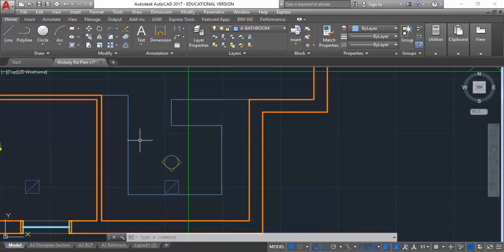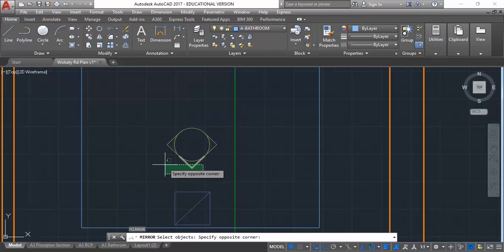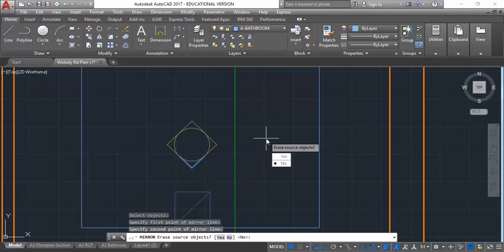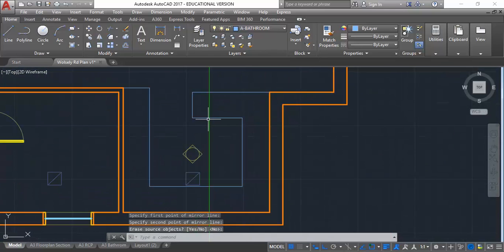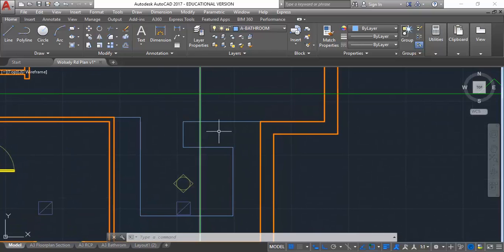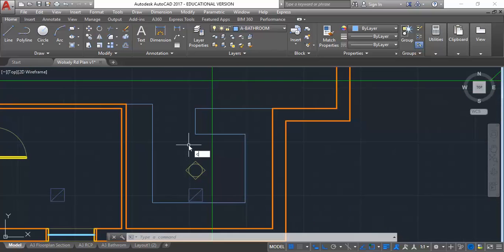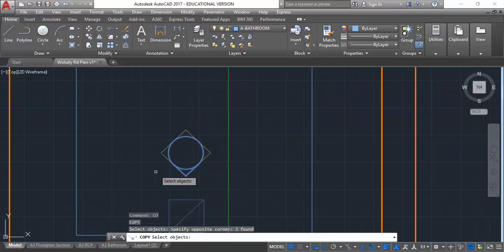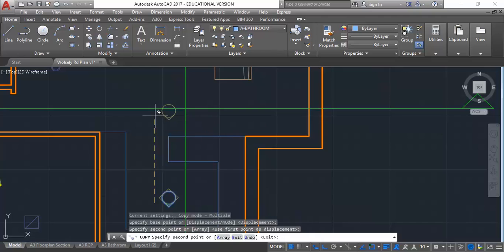Because of the, no, just the plan. So you'd need all 4 sides that you can see from the inside here. So you'd have doors there, doors there, doors here, doors here. So you'd need all 4 directions from that inner area. But then you're also going to have the face of the counter that's visible from up here. So you'd have another elevation for up there, looking towards that face. And that's probably the most important one, because that's the part that's visible from the living space.